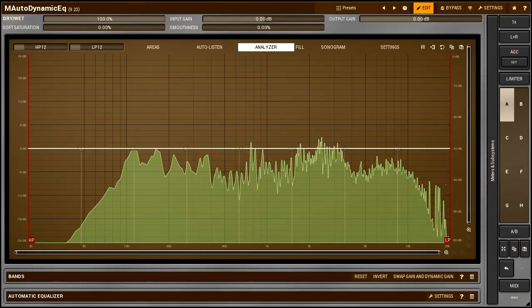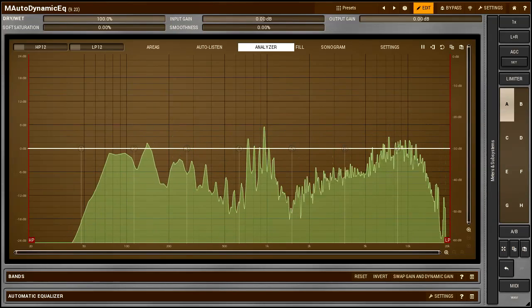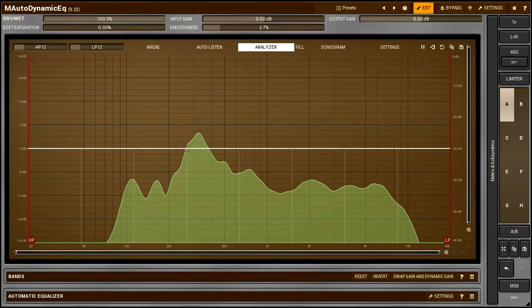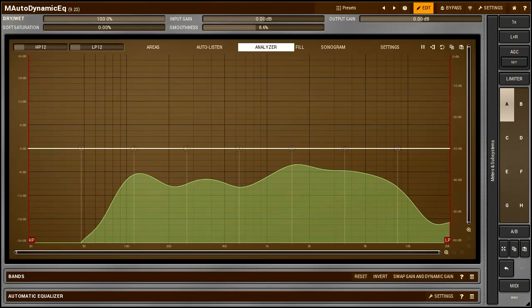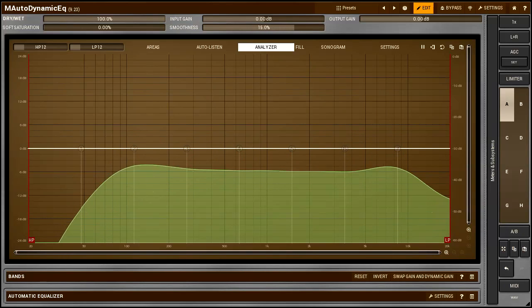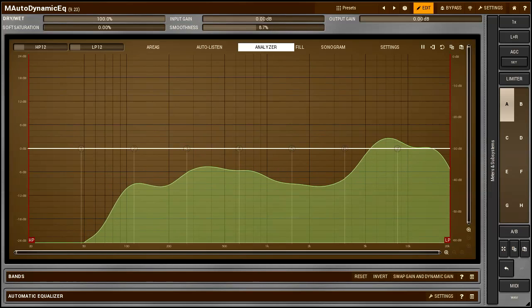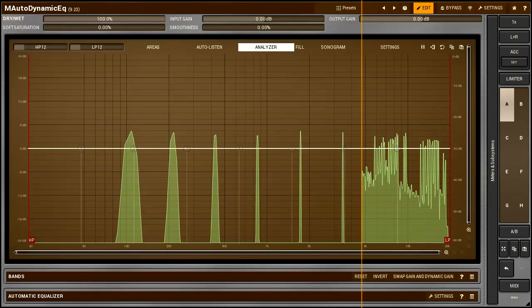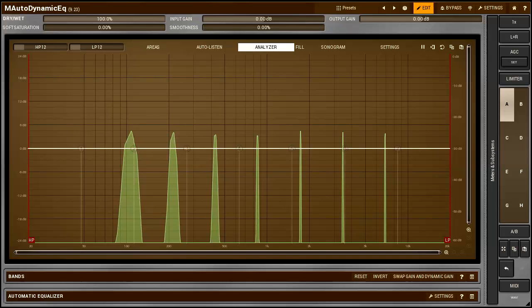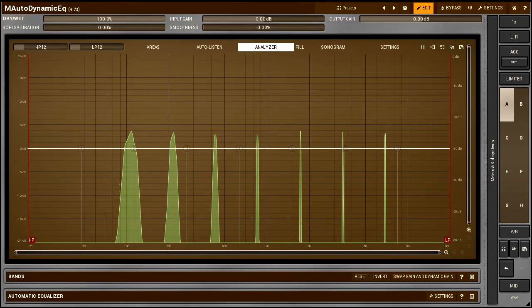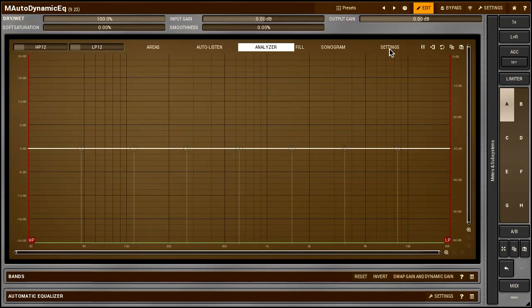All settings that we're about to study are for making the data easier to interpret. And the first parameter that can lighten the graph reading is the smoothness. It smooths out the graph. When it comes to perceiving sound, we assess rather a spectrum envelope than single harmonics. And this parameter attempts to do that by smoothing out the original sharp image of the frequency response. However, it's important to understand that it is not a level averaging. That's why the harmonics at the end of the frequency range, that look sharper, get smoothed out first. So yes, this parameter makes the graph easier to read, but it doesn't approximate the graph the way we perceive sound. Now, let's open the Analyzer Settings window.